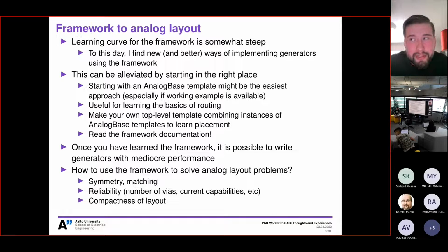But for the vendor P cells, if you want to reuse them in the layout, you need to create pins on top of the vendor P cells that are on the grid. I would say starting with that is probably not the easiest way of learning. Was the question about reusing P cells as the primitives within a generator?